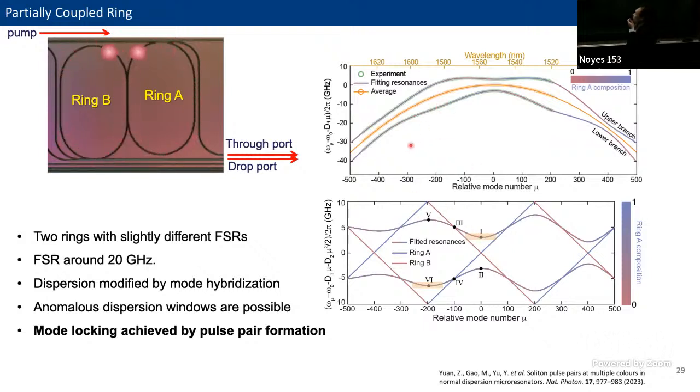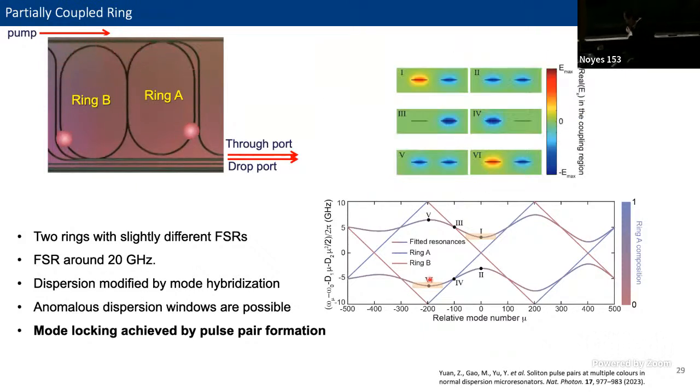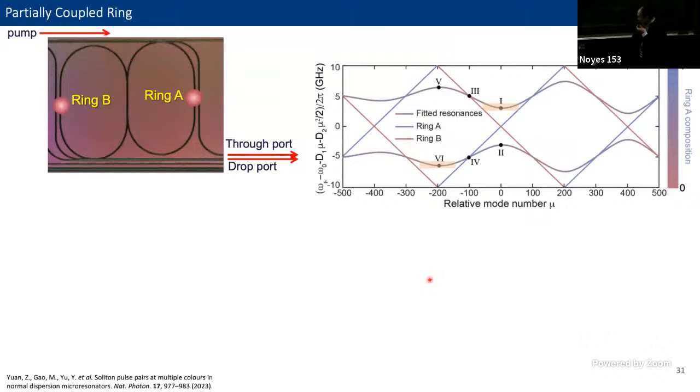In this figure, we are subtracting the overall second-order dispersion, which helps you better identify what is really happening as the two resonators are coupled together. As you can see here, at 1550 nanometers we have the first anomalous dispersion region we are pumping, and consequently further anomalous dispersion regions. Next, I'm going to explain why this coupling doesn't require any mode number matching.